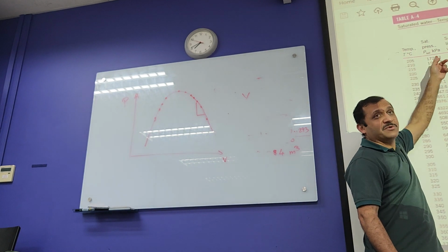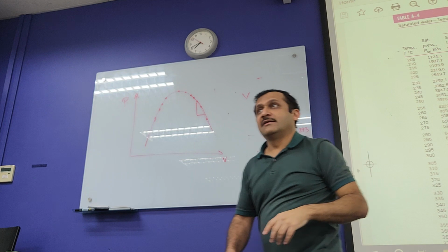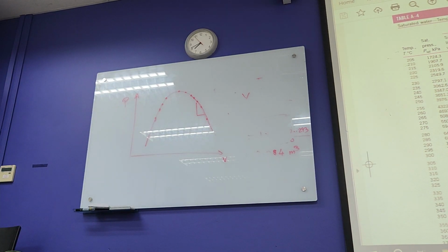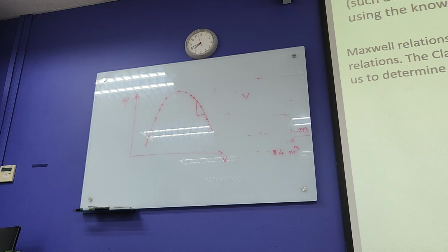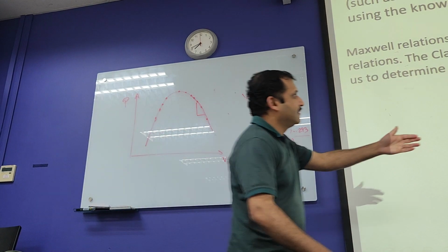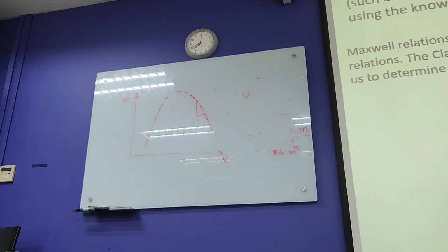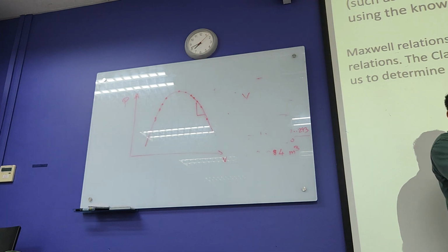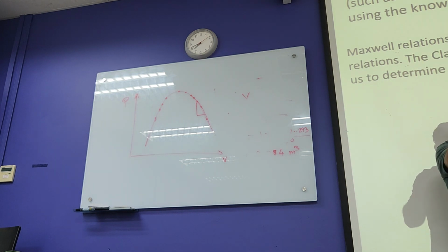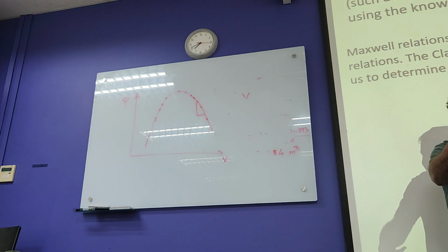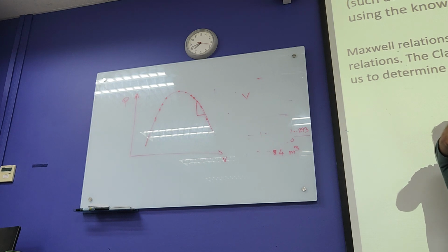These are saturated properties. And knowing that, the change in pressure divided by the corresponding change in temperature gives you that slope. Specific volume: let's say you start the experiment with 1 gram or 1 kilogram of liquid, whatever, and you know the volume of the rigid tank.